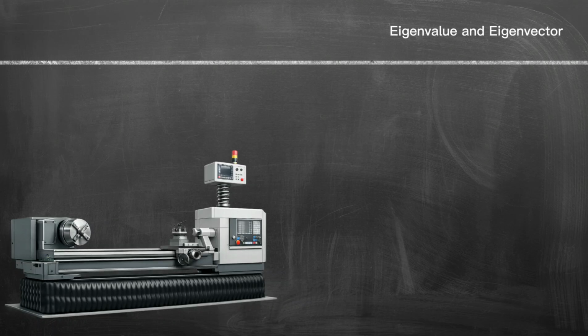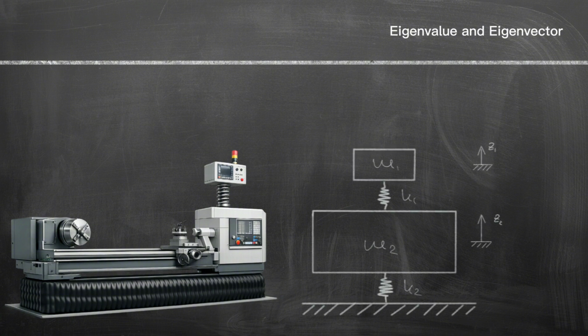In this video, you will learn what an eigenvalue and an eigenvector are, and how they are linked to natural frequency and mode shape in a real-world engineering example. For most dynamic analysis, the shown turning machine can be reduced to a vertical 2-degree-of-freedom oscillator with the masses m1 and m2 connected via the spring K1 and the spring K2 as the foundation stiffness from m2 to the ground.